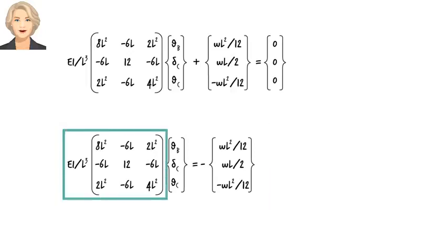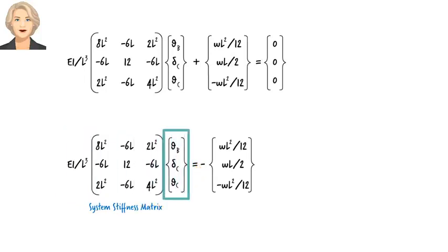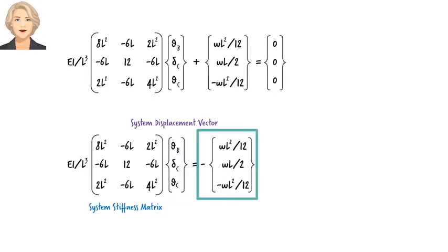This is called system stiffness matrix. This is system displacement vector. And this is system force vector. There are various methods for solving such system of equations. If you are going to solve this by hand, Gaussian elimination method would be a good technique to use. I am going to assume that you know how to solve this already and just present the results here. The solution for this system is...